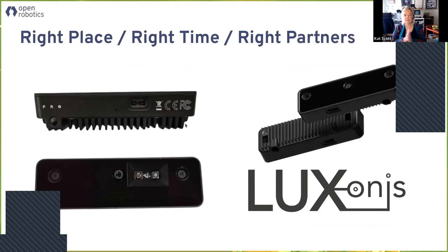So one other thing you mentioned, computer vision and LiDAR, but are there other sensors like the touch sensor and other things also there, right? Yeah. So on most of the mobile bases, there is a cliff sensor, a bump sensor. Some of them have like a 1D, 2D LiDAR. If they're a vacuum, they need to figure out where the edge is, so they at least have that. IMU, but I'll talk a little bit about what's in there.